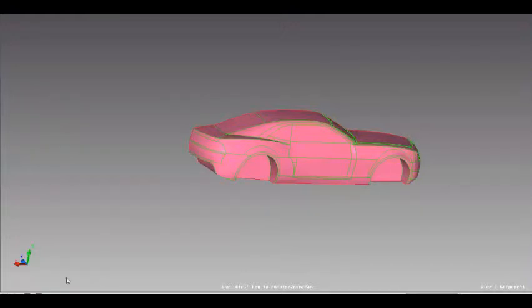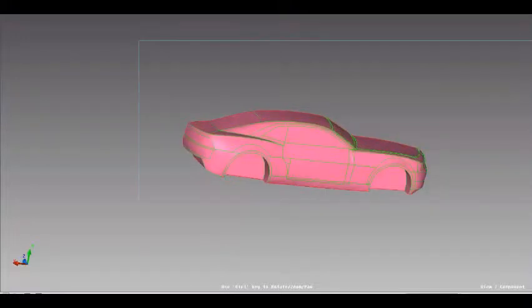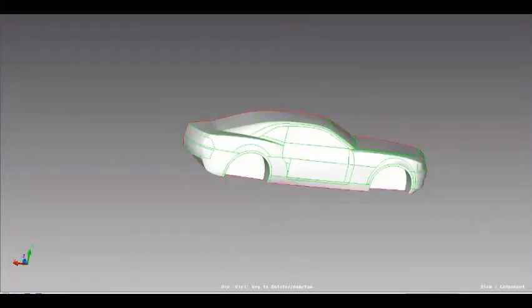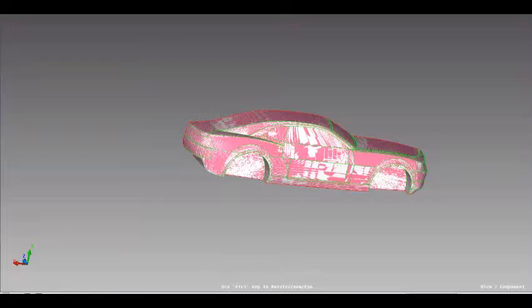And once I select all my options, a user has to just input the mesh quality, which is the min, max, and the average element size. So once the user specifies this, we just need to select the surface and say preview and execute. So generally to generate this kind of mesh, it takes a couple of minutes. So in the interest of time, I want to demonstrate the existing mesh which is generated using the same process.